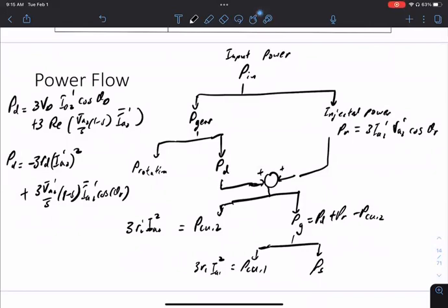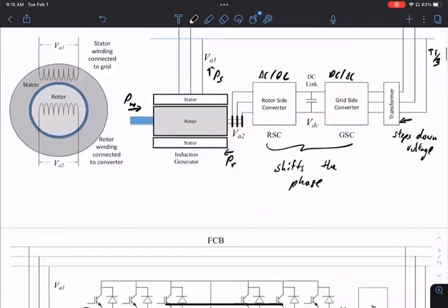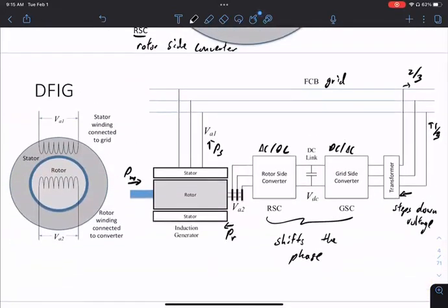Oh, so that's the amount the grid gets. That's a good question. If you go back to this diagram, this is PS and PR coming here. The grid normally operates by demanding a constant power output. The thing is, you have a generator. From the grid operator's perspective, for example, I allocate resources, so this generator will provide 2 megawatts. I want this generator to have a constant power output, so I want these two sums to be constant. But then S changes here, so I need to track them. Any other questions?